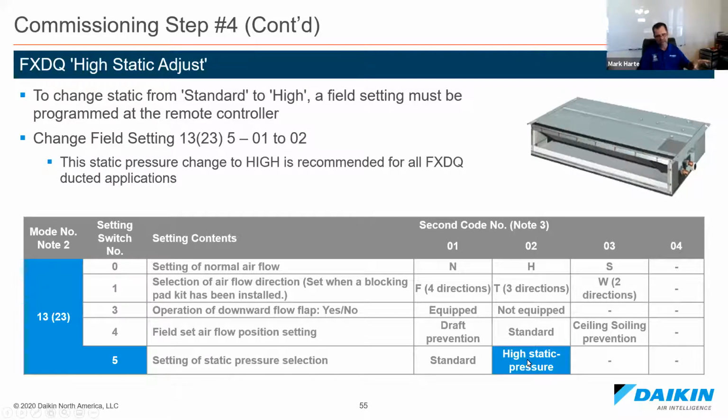You're not getting a lot off this. I think the 2 ton, you can get up to 0.24 static. You're not going to be running 100 feet of ductwork off of this thing, okay? It's low static. It's designed. I see a lot of them in the hotel rooms where they have a short run of duct, where they just have a supply grill and a return grill, and that's it. Very quiet fan coil, very quiet, good for hotel rooms.